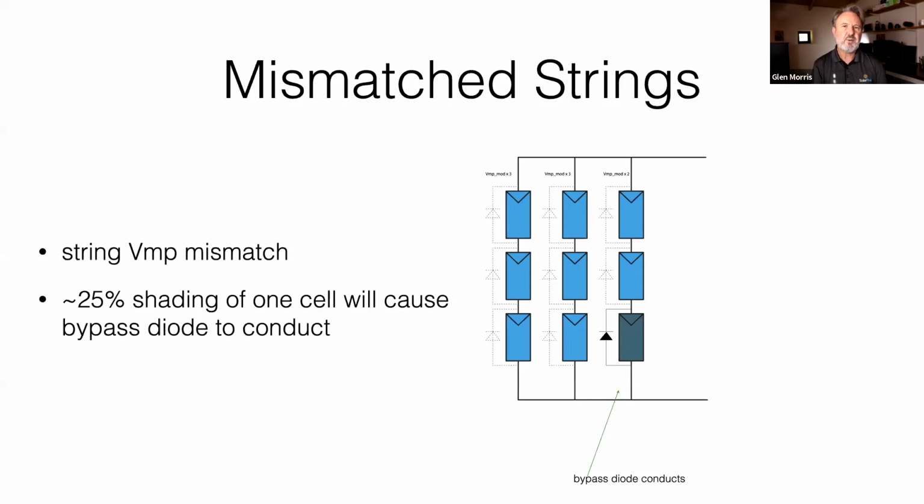But we have a requirement that all PV modules have an inbuilt bypass diode, or diodes. There's generally multiple diodes in modern panels. And a bypass diode is there to protect against overheating due to partial shading. It also allows current to flow around a shaded panel and not effectively cripple the output of that string.